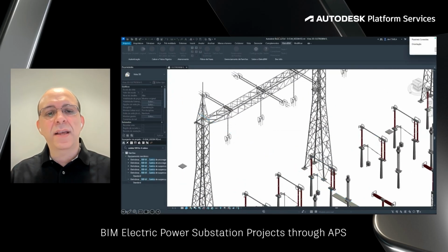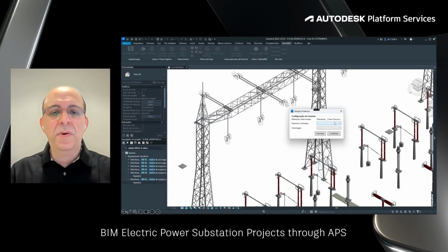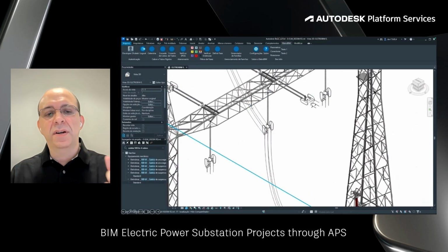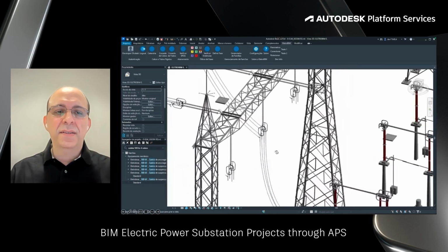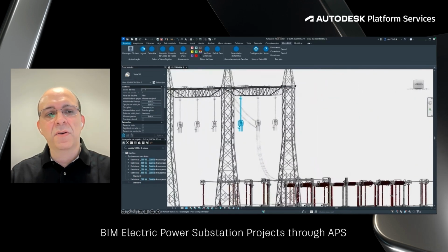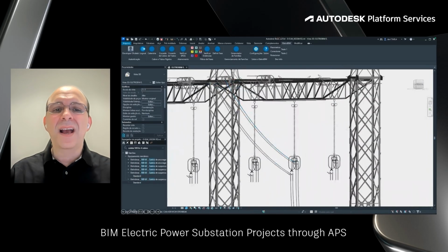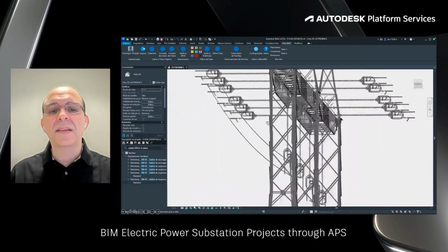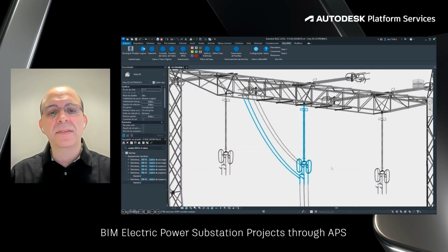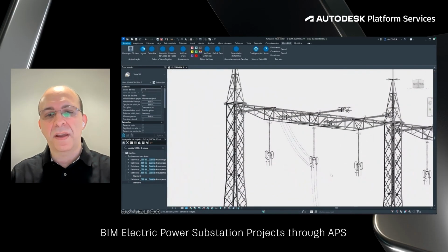You've seen a bit that once I specify the connection points on both ends, again, this is based on the voltage and the infrastructure design requirements. So the 4 cables are designed, and if necessary, in this case it wasn't, it creates the spacers to accommodate that. So you can easily see how complex it is to deal with these things in 3D, and Revit does a great job dealing with those elements in all their required level of detail.